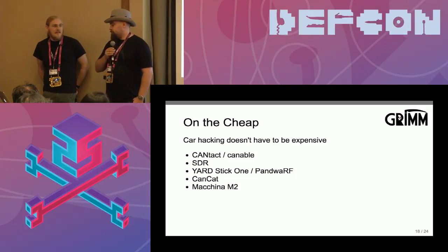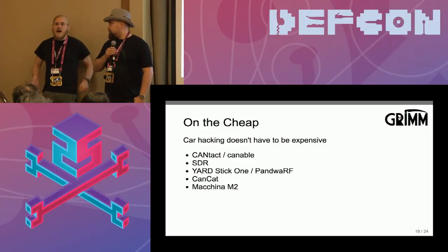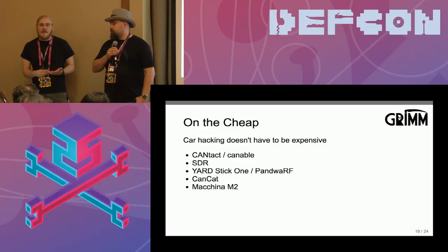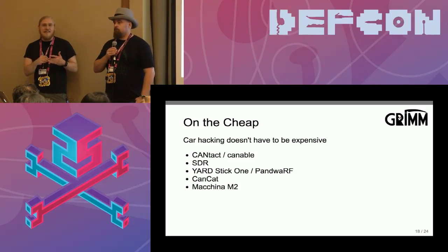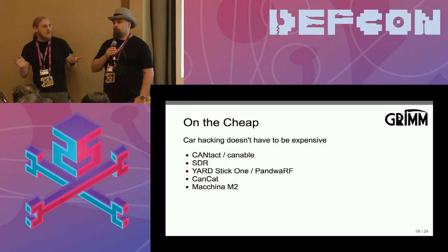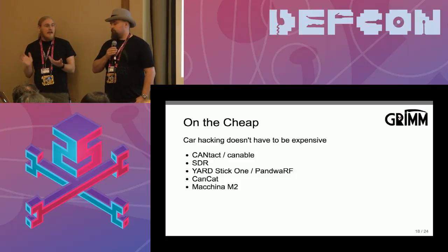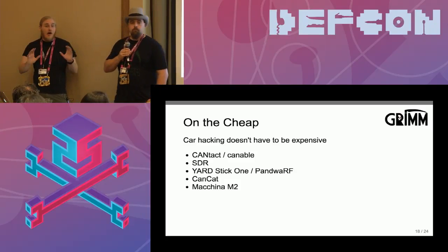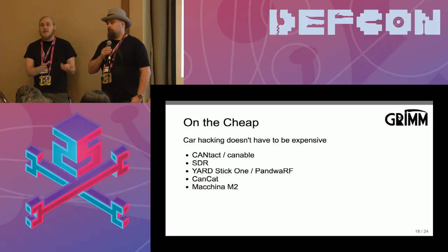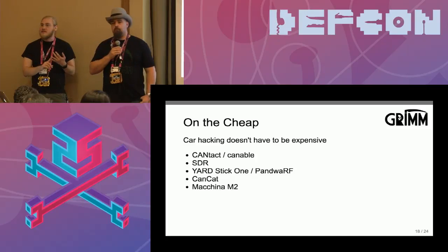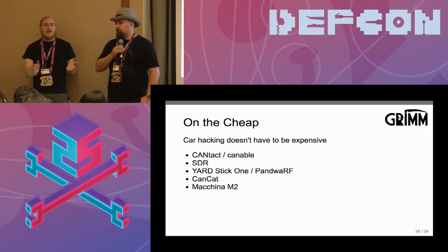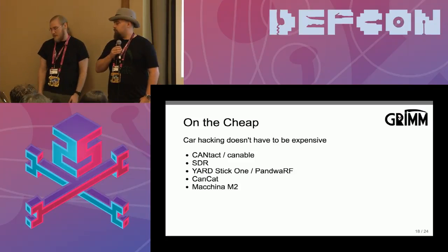Yeah, that too. If you want to use SDRs, the most common way of interfacing with them is with something like GNU Radio Companion, which is a very complex flowchart-based radio setup tool. The Yardstick One and PandwaRF are all in hardware. So it's configurable, and it does multiple modulation types and encodings. But you set the hardware up, and you just do the data transfer. It's much simpler to use.